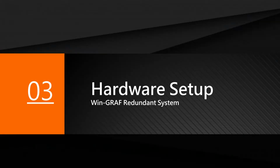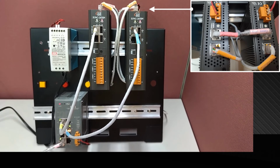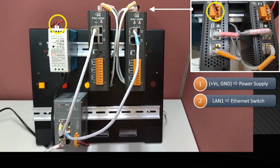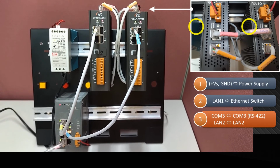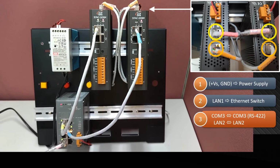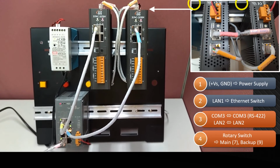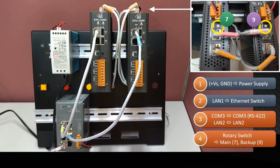Hardware setup. Before configuring the redundant system, set up the hardware properly. Both powers and LAN 1 ports have been connected in the previous step. Connect COM3 to COM3 and LAN 2 to LAN 2 by using Ethernet cross cables. Set the rotary switch of RPACs to 7 and 9 and then power on.